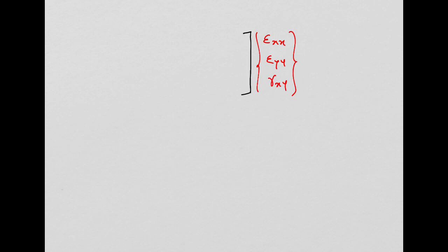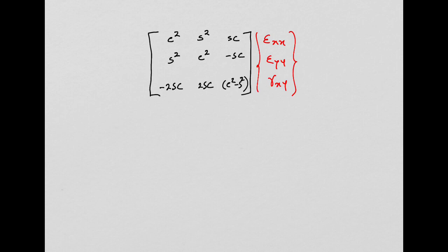So I need to multiply this by my transformation matrix. Okay, this is my transformation matrix. And then if I do that, what I obtain is my strains in the laminar coordinate system.